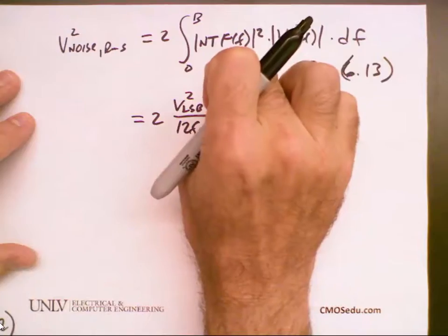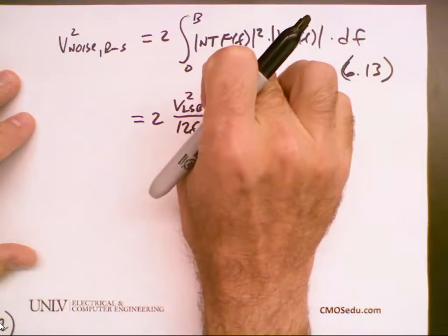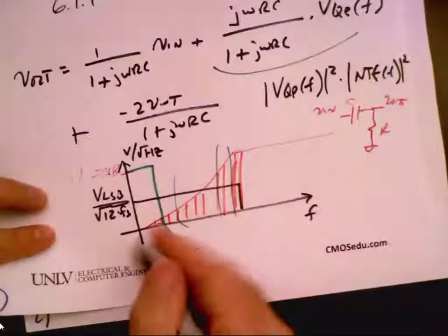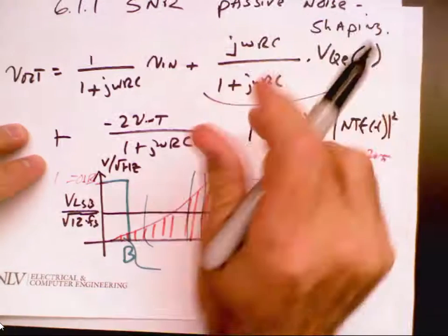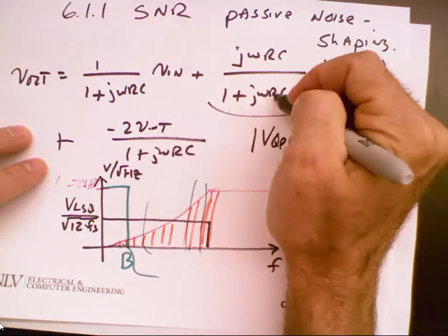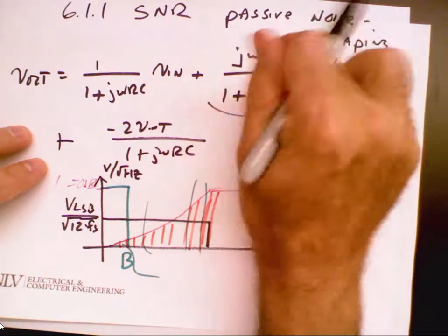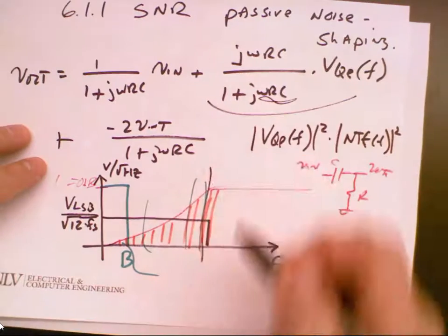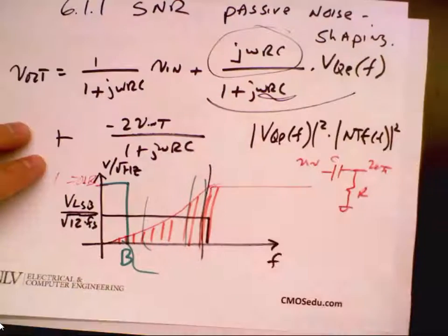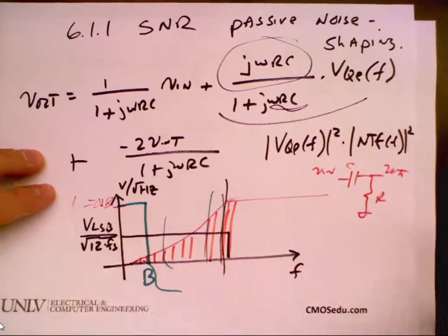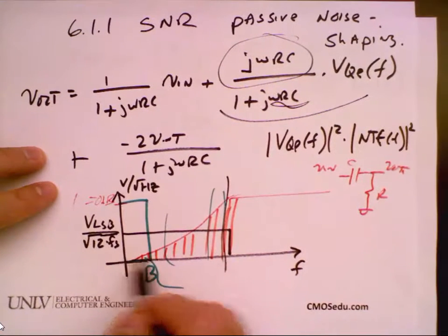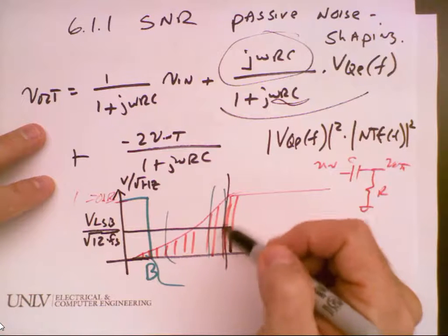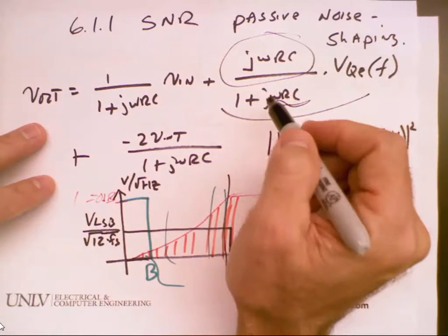And then this term here, so the assumption here is that we're staying at low frequencies. So this transfer function is approximately just 1 over, it's just the DC portion. In other words, we're staying away from the 1 over 2 pi RC here, so that the transfer function is approximately just this. Did I lose anybody there? So if we band limit our filter so we're over in the lower frequencies, then we're not going to have to worry about the pole, so I'm not going to carry it through the integration.